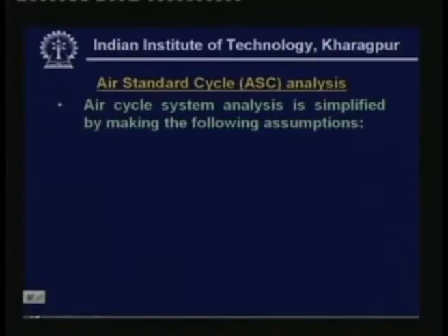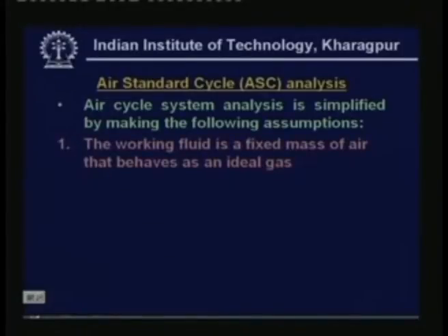Before we take up the various cycles, I would like to mention here an important type of analysis known as air standard cycle analysis. Air cycle system analysis is simplified by making the following assumptions. The first assumption is that the working fluid is considered to be a fixed mass of air which behaves as an ideal gas.